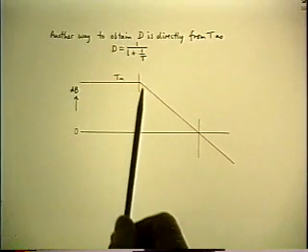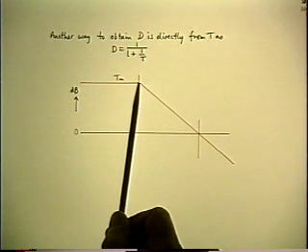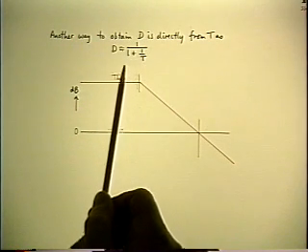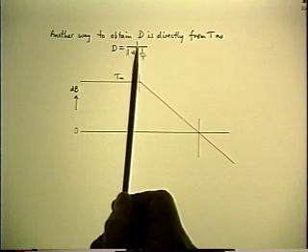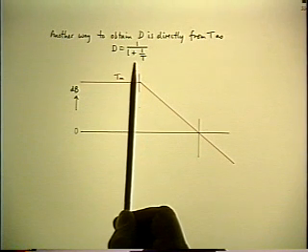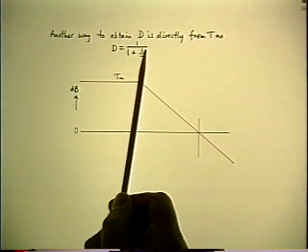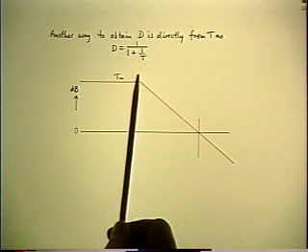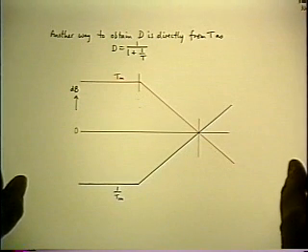Back to the loop gain we started with, the single pole function. The ultimate objective is to find G, the closed loop gain. So one of the steps along the way is to find D, which is T over 1 plus T. But if I rearrange the expression like this, it changes the algorithm, because the graphical sequence is now different. So I start with T, and the first thing I have to do is find 1 over T. That's a reciprocal. That's a vertical inversion of the logarithmic scale. So 1 over T looks like this.